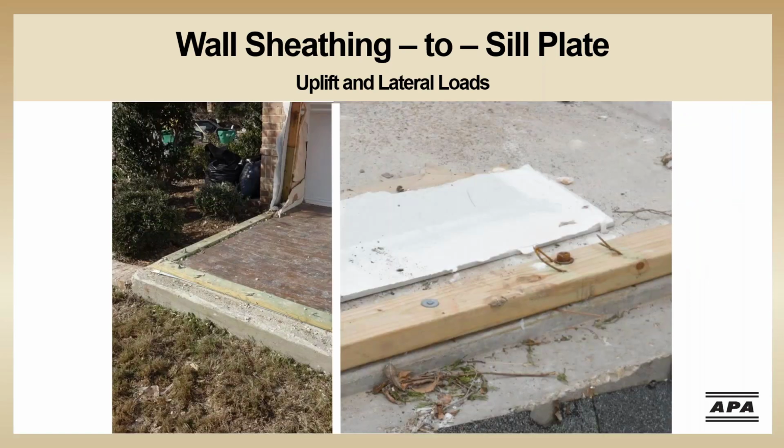Looking closely at these photos, you can see that there don't appear to be any fasteners at this critical connection. As a result, the wind load simply pulled the wall assembly away from the sill plate.